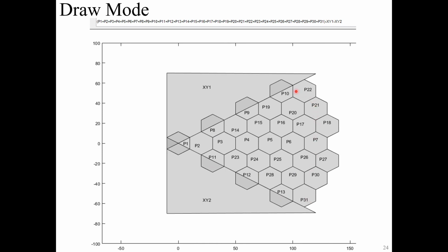When you generate those hexagon assemblies, you need to learn how to enter and when to enter the negative displacement. For example, when you generate those assemblies, you need to enter the negative for the y. And draw another two triangles. Draw these two triangles to cover the upper diagonal line and also the lower diagonal line. Do not forget to adjust your set formula: the union of all the hexagons minus the two triangles.